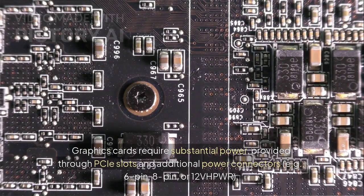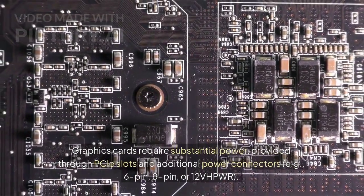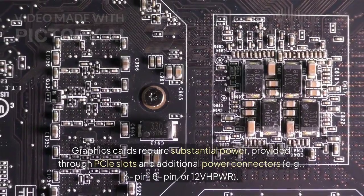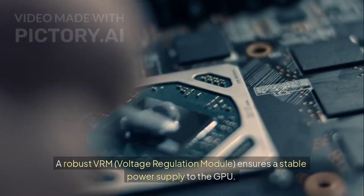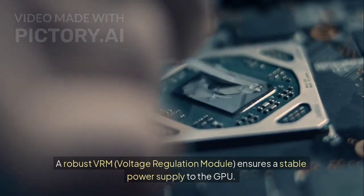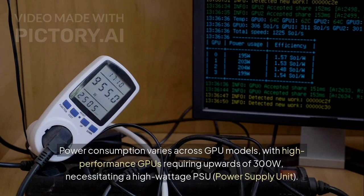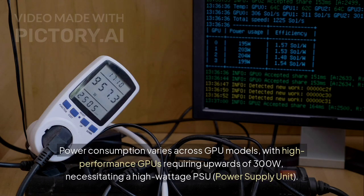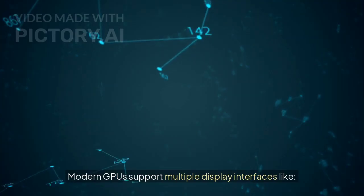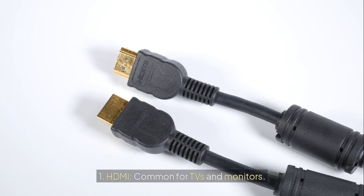3.5 Power delivery system. Graphics cards require substantial power, provided through PCIe slots and additional power connectors, e.g., 6-pin, 8-pin, or 12VHPWR. A robust VRM, voltage regulation module, ensures a stable power supply to the GPU. Power consumption varies across GPU models, with high-performance GPUs requiring upwards of 300 W, necessitating a high-wattage PSU, power supply unit.